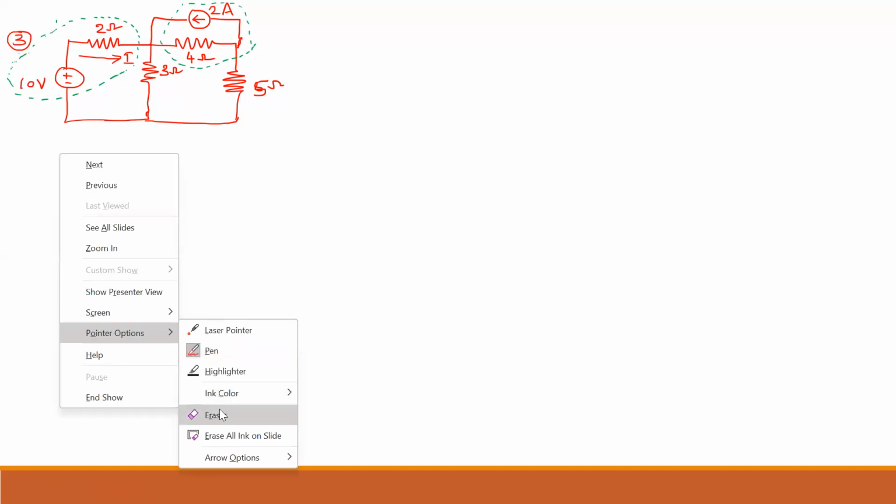Now, if you observe these two, as we have to find the current flowing through the 2 ohm resistor, we should not disturb the particular 2 ohm resistor branch. That's why, even though we can apply the source transformation over there, don't apply it there. You should not disturb the 2 ohm resistance branch. So you just leave it as it is, the 2 ohm resistor.